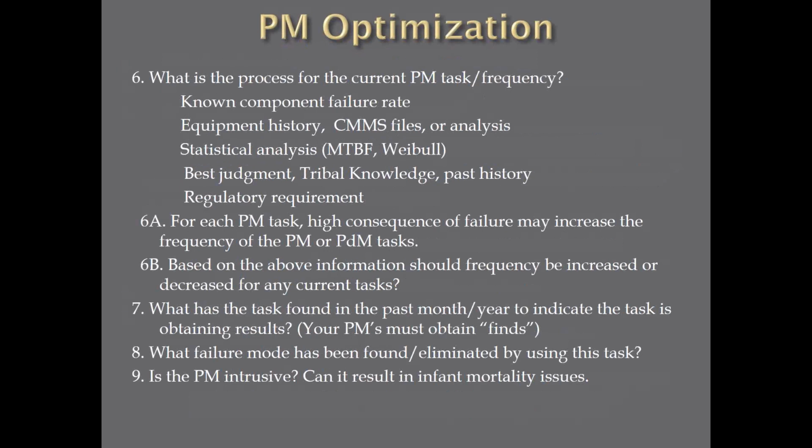Number 9, is the PM intrusive? Can it result in infant mortality issues? I'll give you an example that happened at my facility. A maintenance person changed oil in a centrifuge and used the wrong kind of oil. Within 24 hours, the gears in the centrifuge failed. So here the PM task was kind of intrusive, right?